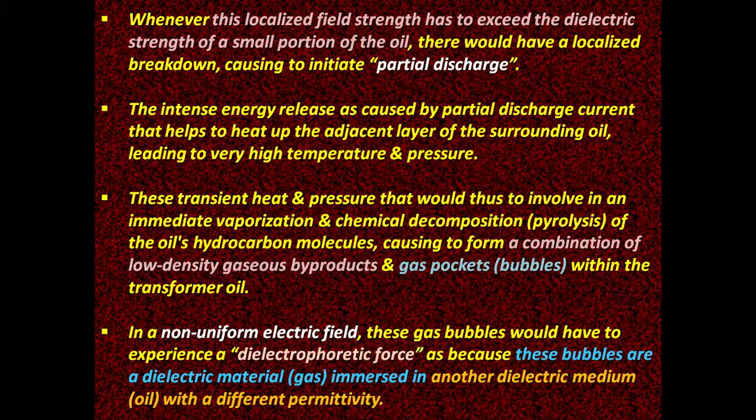In a non-uniform electric field, these gas bubbles experience a dielectrophoretic force, because the bubbles are a dielectric material, that is, gas immersed in another dielectric medium, oil, having a different permittivity.